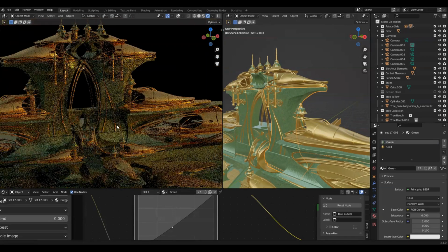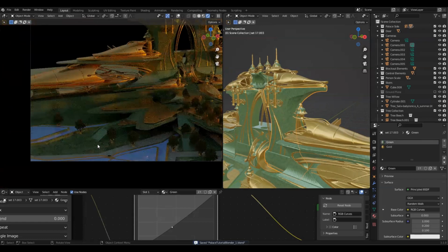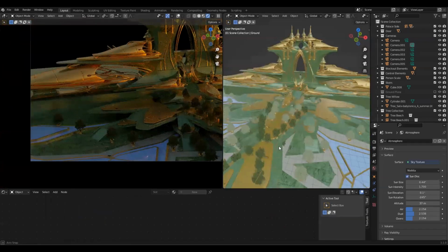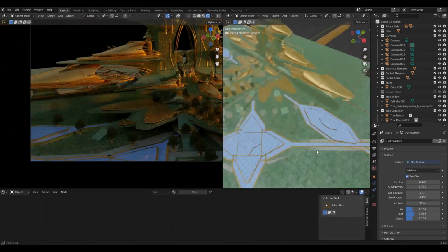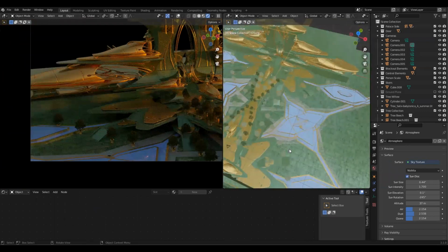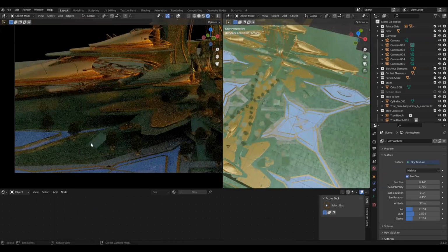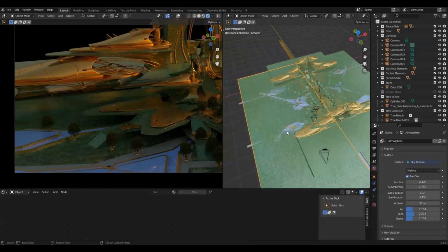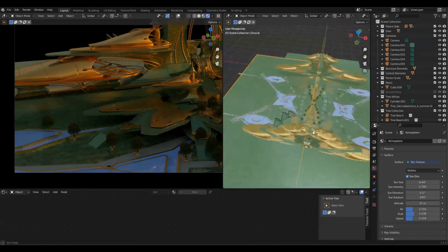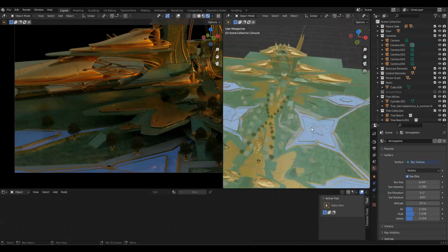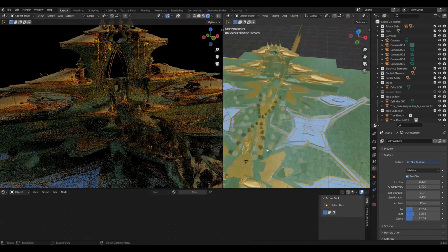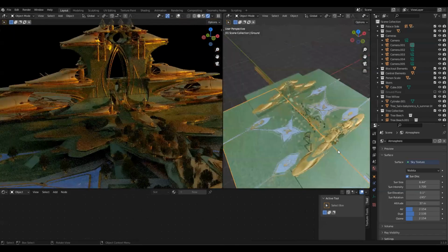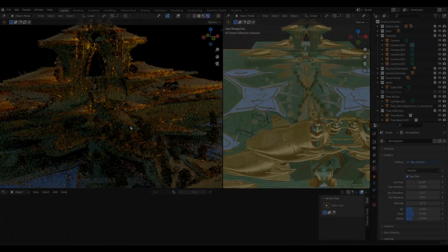So that's great. Now the scale of these tiles on this ground plane is looking a little bit too big in relation to everything else. And I think that is because of the way those elements were set up. So we might need to create a separate material for that, and then we could copy and paste all the nodes into that material and just shrink the scale a bit. That would be one fix, but I'm also thinking that whole ground plane might be something else entirely. It might be grass, or maybe some other type of stone. So let's not worry about that just yet.